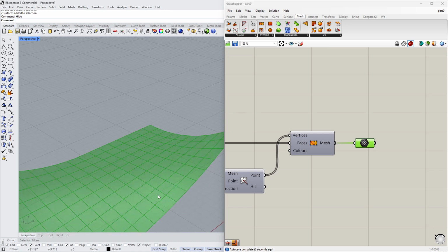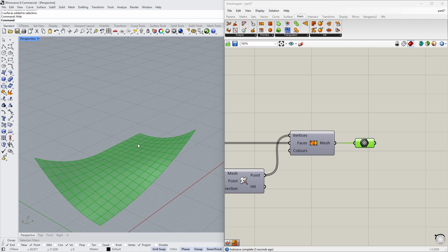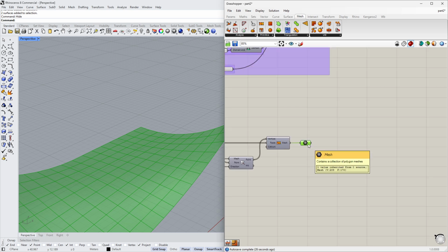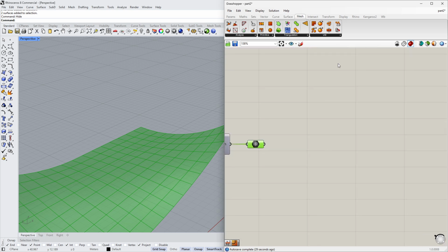Unfortunately, all these panels are double curved, and we don't want that. We want them to be flat panels, so they're ready to be manufactured. And also, we can directly use that rationalization process of flattening those panels to get that staggered effect of the roof. So what do we need? We need the corner points.